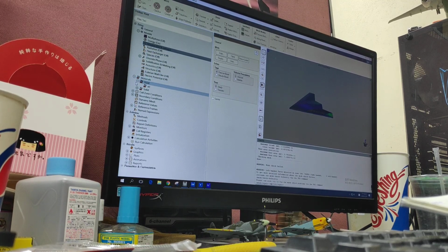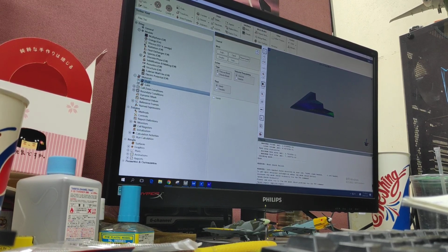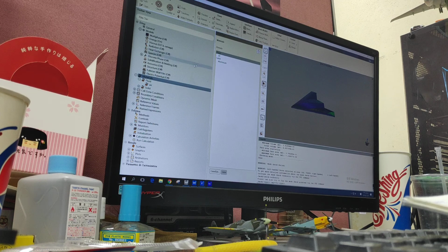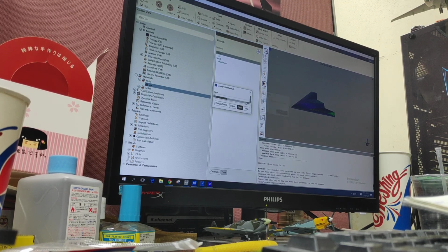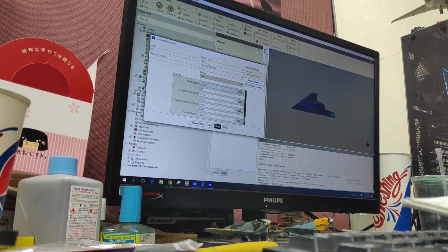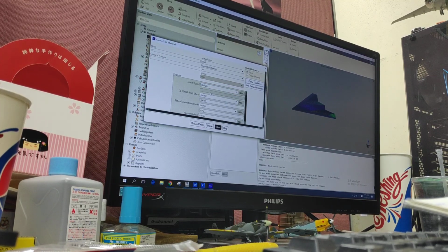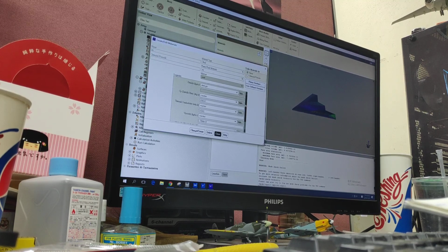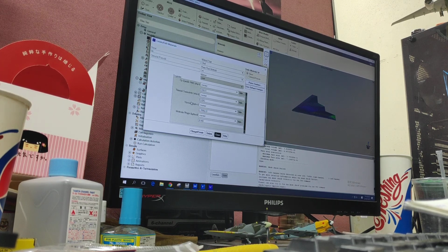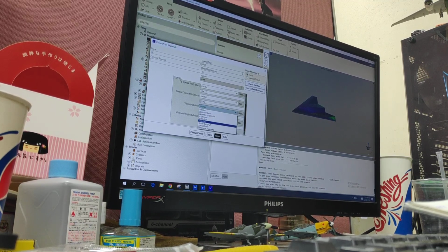Okay, materials, because you say you are using water, right? Water, I want to use that water channel for experimental. Yeah. But here I want to use the air. Oh, okay. So we don't need to change this. Okay, air. We have to click here. Okay, fluid. If your density is constant, that means you have incompressible flow. But if you are using ideal gas, this means compressible. Yeah, compressible. And if you are at a high Mach number, you have to. Okay, your viscosity, you have to change to 1000.